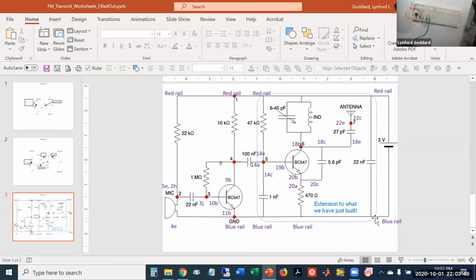So this is going between the red and the blue, but currently I'm not using this top blue rail. So in order for me to use it, I need a jumper wire between the bottom blue rail and this top blue rail. So this one, I'm actually just going to put very, very far away. So I'm going to put this between 5 and 1, or 3 actually, of this blue rail. So what I've done here is I've plugged in a jumper between this bottom blue rail and this top blue rail so that it's more convenient for me to plug in the capacitor. It'll also be more convenient when I plug in the battery, because now the battery clip can just go on one side rather than having to span the two. So I've connected the blue rail here to the blue rail there.